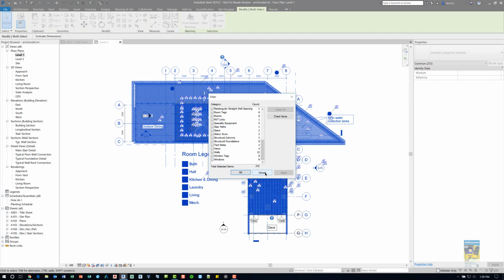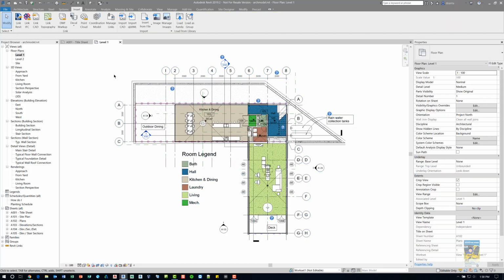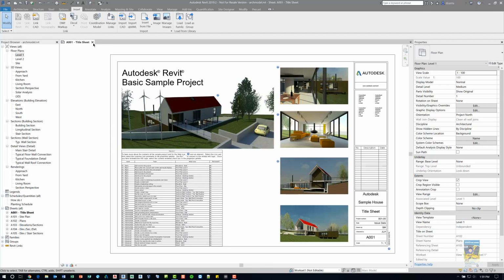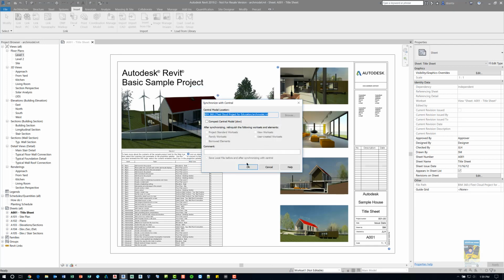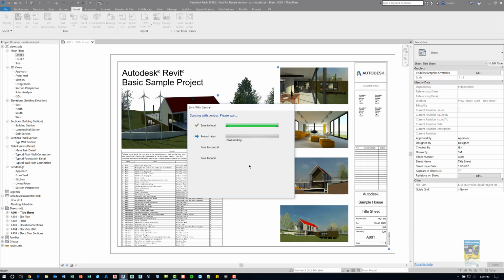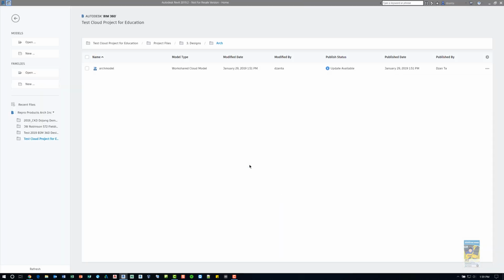Okay? Now, the whole purpose of linking in another Revit model into a host Revit model is so that you can use the copy monitor functionality. I'm going to explain this when we head over to the MEP aspect of the model creation. So for now, I'm going to save my work and get out of this file and save it back to the cloud.